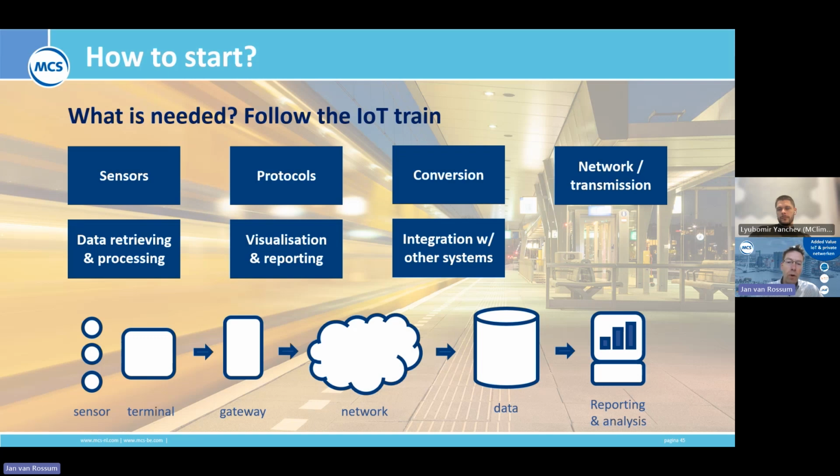So you would like to collect the Modbus data and then push the data through the LoRa network. So you need specific devices that can translate that data, do some kind of protocol conversion, what you see over there, and then get the data on LoRa.